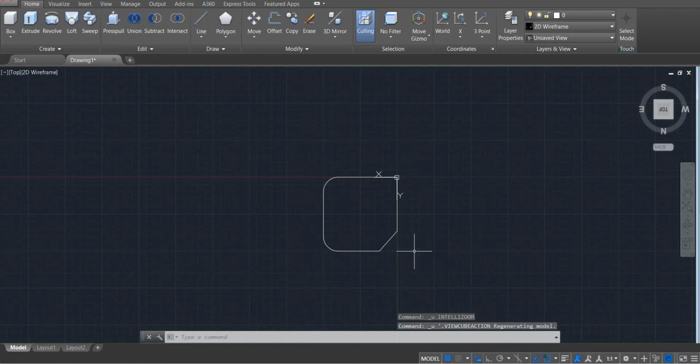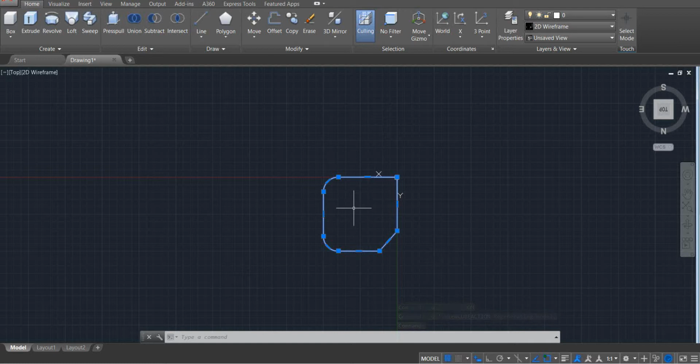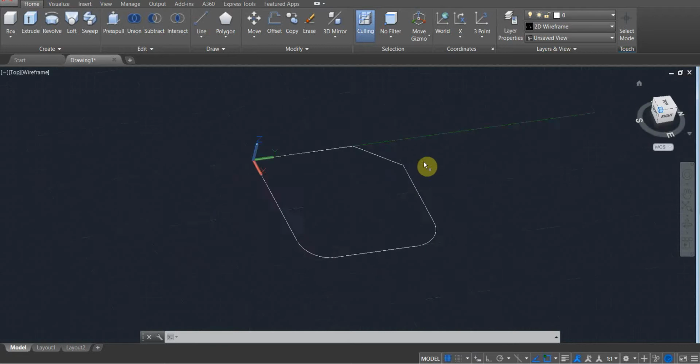Also, this is not it for the extrusion. Extrusion has lots of options. The default is that we extrude this section in one specific direction, perpendicular to the cross section, whatever in the top, going up or going down, but it is perpendicular to this line. But we can do other things. There are more things that we can do using extrusion. We can adjust the way of extruding this object. How? One of the options, for example, is going to be much clearer if we work in 3-dimension.